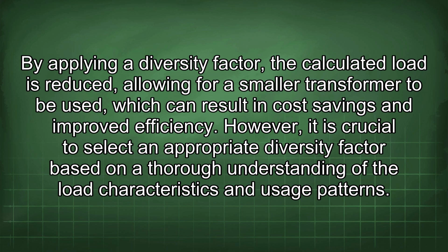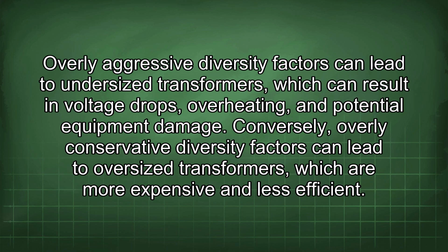However, it is crucial to select an appropriate diversity factor based on a thorough understanding of the load characteristics and usage patterns. Overly aggressive diversity factors can lead to undersized transformers, which can result in voltage drops, overheating, and potential equipment damage. Conversely, overly conservative diversity factors can lead to oversized transformers, which are more expensive and less efficient.